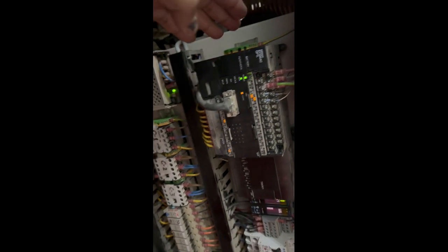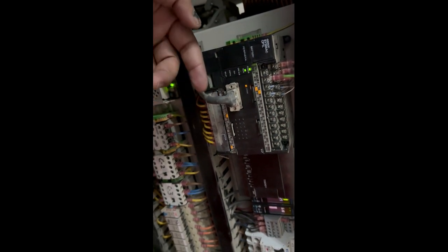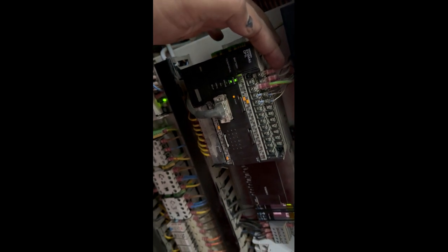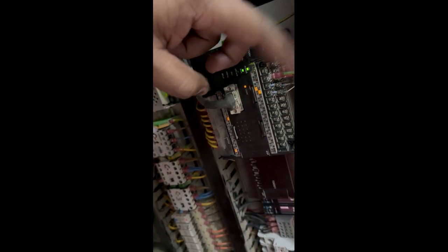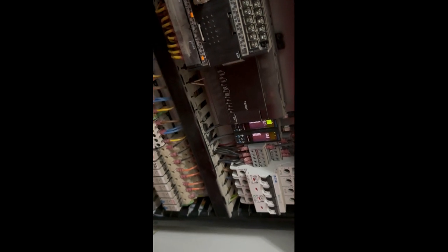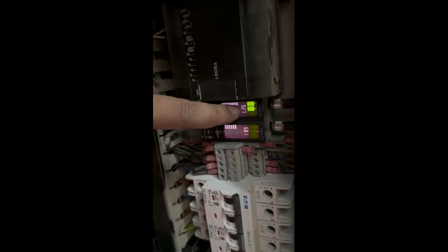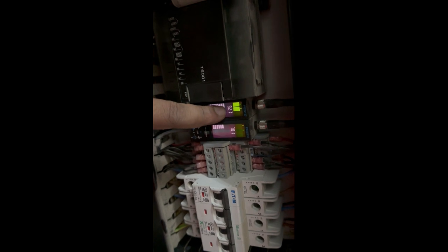Here in the geometry of the system, we have the PLC, and here we have the communication cable for the PLC. These are the power supply cables, 24-volt power supply, and the rest of the inputs and some outputs are also there. Here we have the IO card, input output card, and the pressure switches, the pressure switch for nitrogen, and here is the pressure switch for air. Here you can see the pressure. This is the pressure switch for the nitrogen, and set point A and set point B both have been reached.